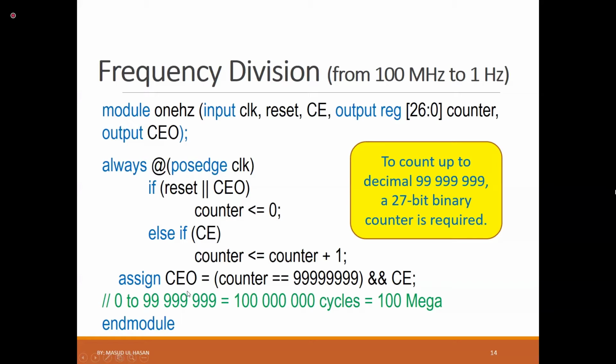Here also we are not clock gating, but this is a different thing. This is cascading of 2 more 10 counters. That's not my question. Your question is, is it clock gating in this situation? No, it is one counter only. I mean we make this 1 hertz to put it into the clock input of the digital counter, right? Yes, now I understand what you mean by clock gating. Means clock gating between the provided FPGA clock and the clock going to this circuit. Exactly, yes. Yes, this is your question. Yes, very good question.